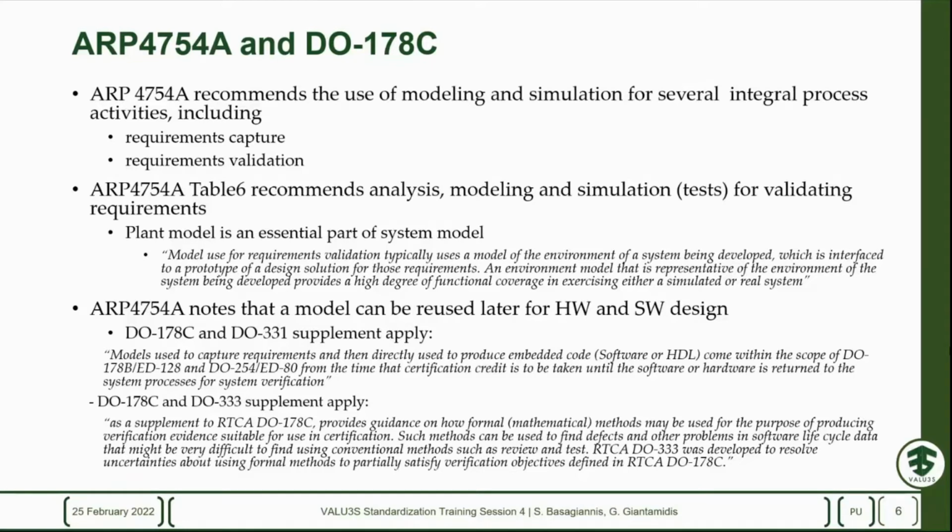Like, for example, the ARP 4754 recommends analysis, modeling, simulation, and obviously testing for all of these requirements, which has to be used, let's say, from the system that we need to validate. So, if you're asked, do we have aircraft models? Yes, but not to the extent. Don't imagine that there is a complete, full-fledged, detailed aircraft model that we are able to use for this requirements testing.